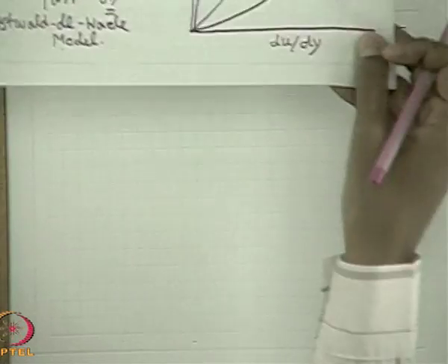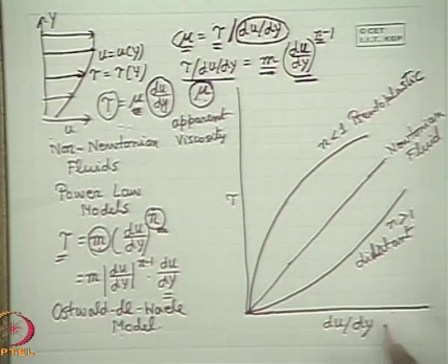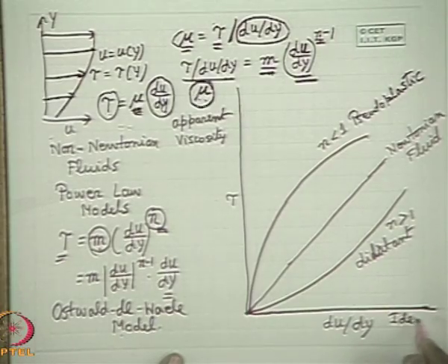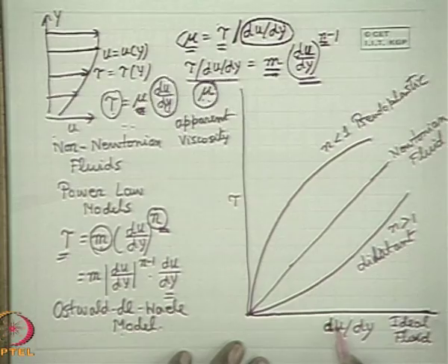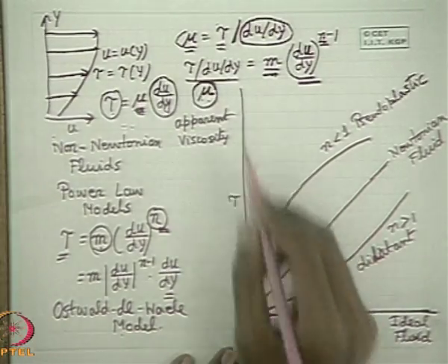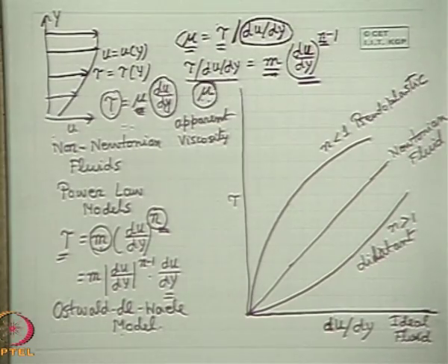So if we see this curve, the abscissa represents ideal fluid. Why? If the viscosity is 0, whatever may be its flow condition or velocity gradient or rate of shear strain, there will be no shear stress developed in the flow field. That means flow of an ideal fluid is devoid of any shear stress in the flow field. The shear stress will not be generated.